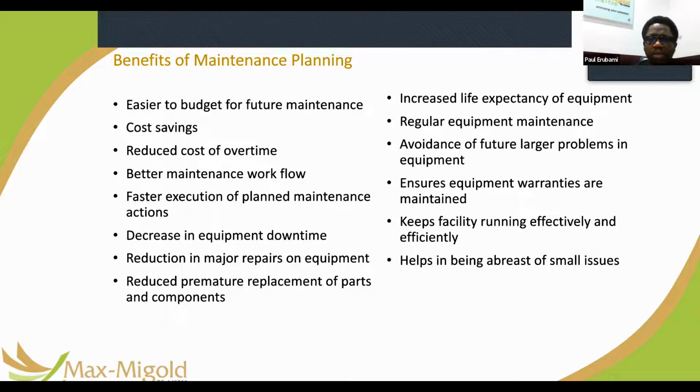This job we're servicing at 250 hours. Do we still need to be doing 250 hours, right? So that's exactly the kind of question you ask. And there will be reasons adduced for either extending it beyond 250 hours or bringing it down to 150 or 200 hours, because you understand the equipment and its condition at that time.